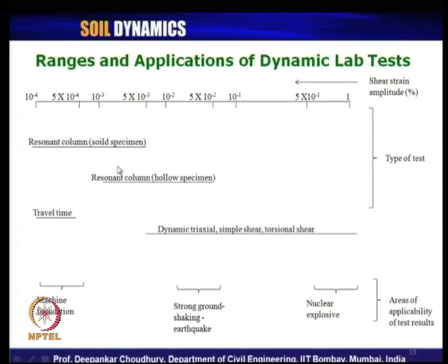So, you should not only have an estimate through a field test of Gmax through the Vs value, but also you should do a cyclic test for your sample at the laboratory. Better to use the triaxial or simple shear or torsional shear with cyclic loading.